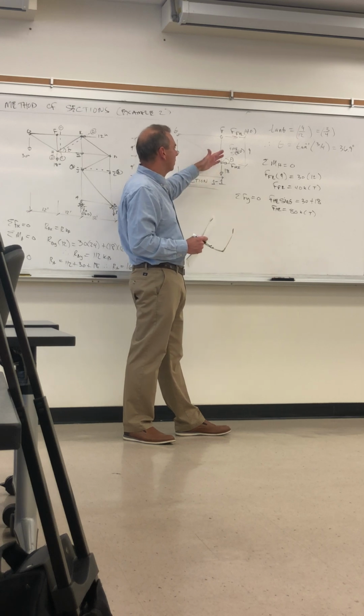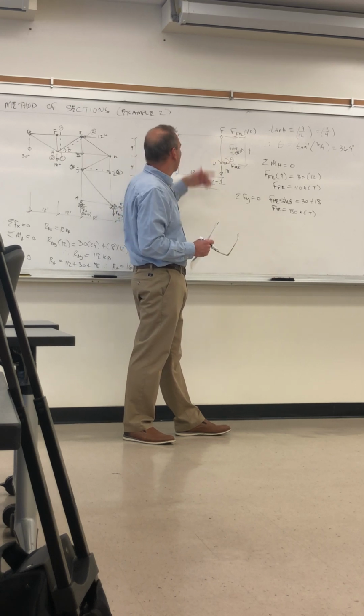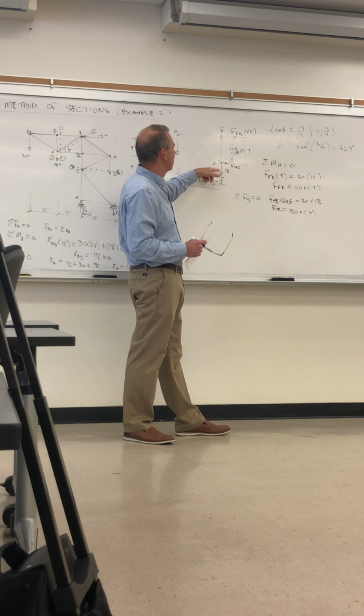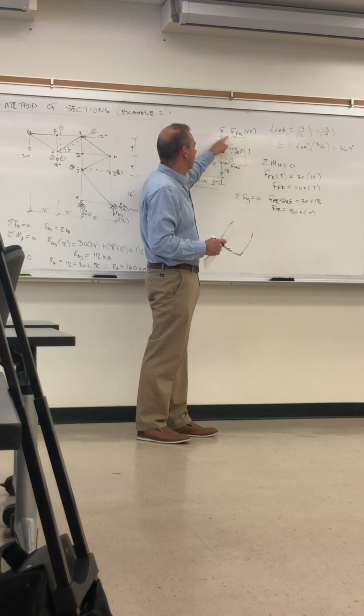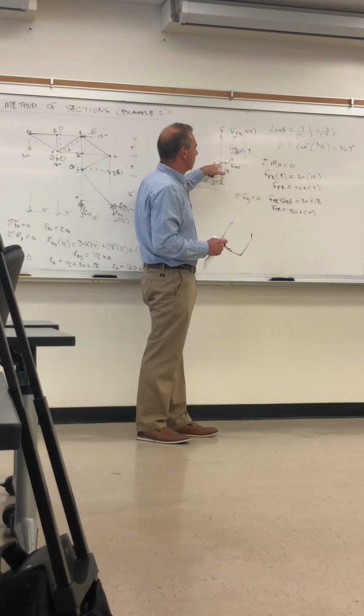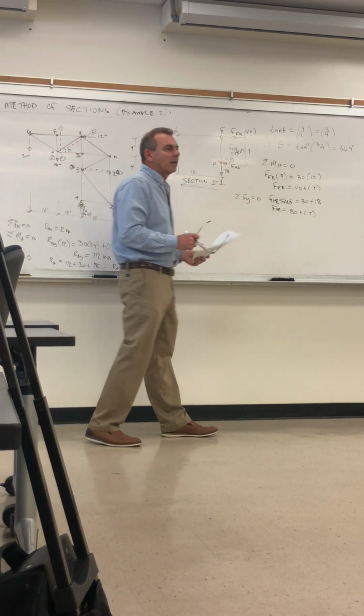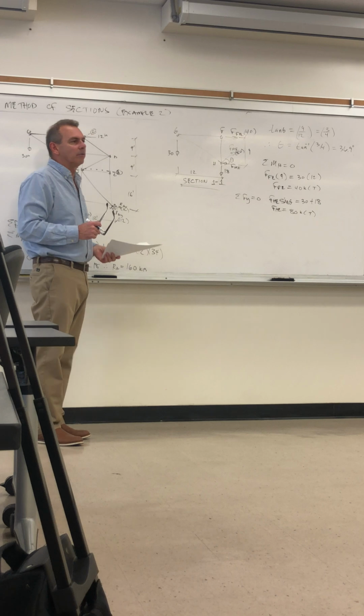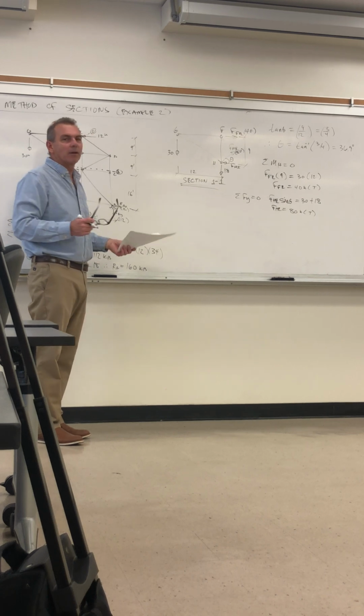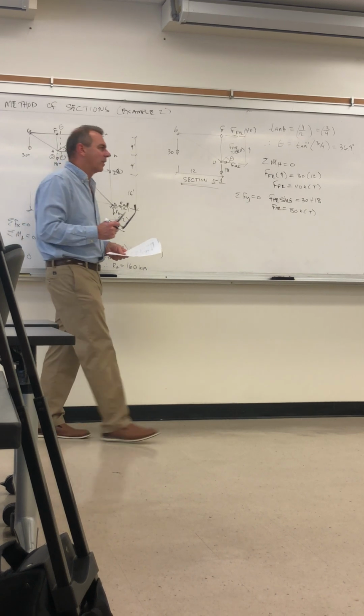But if you don't have a direction, then you can't sum, just like summing moments here. If I hadn't drawn F of FE to the right, I couldn't have summed moments of that here. I wouldn't have known how to do that. But you absolutely need to define a direction, and it doesn't matter which way. Don't spend too much effort thinking about it.